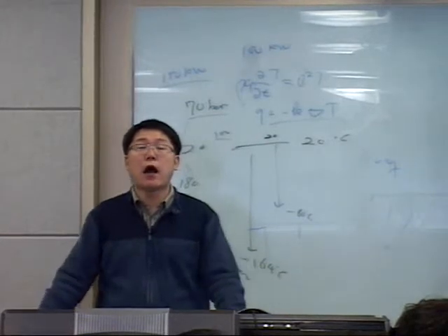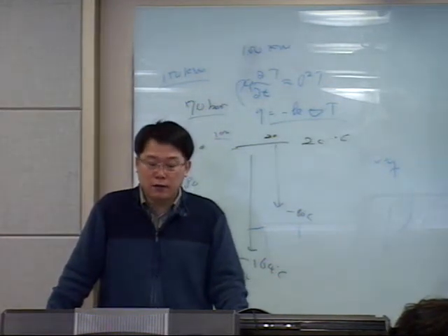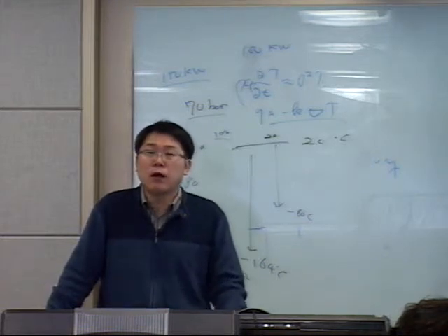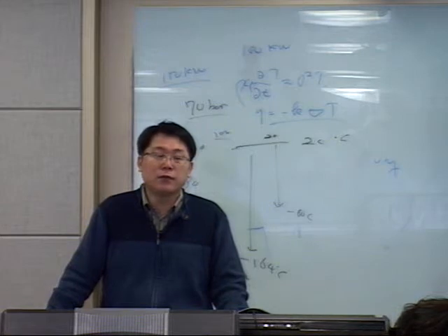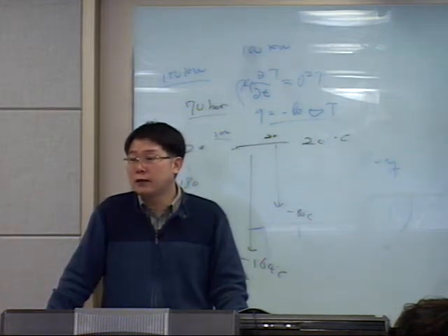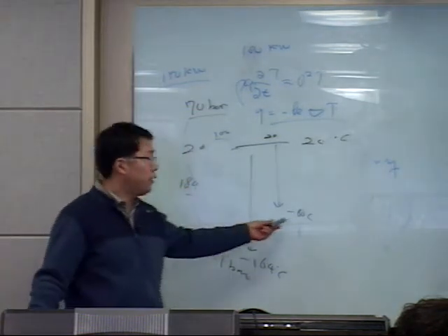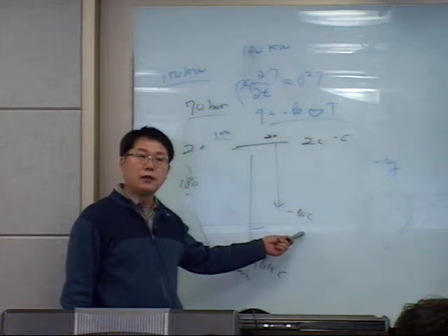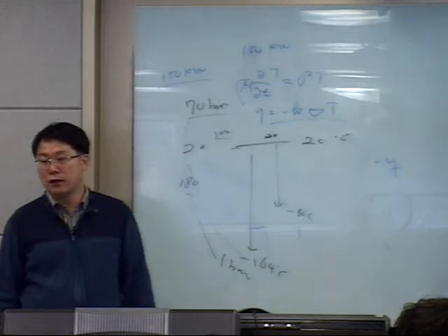That means the cargo tanks should be huge, and that means the pressure vessel should be huge. It's very difficult to construct that kind of pressure vessel, which should withstand 20 bar at minus 80.